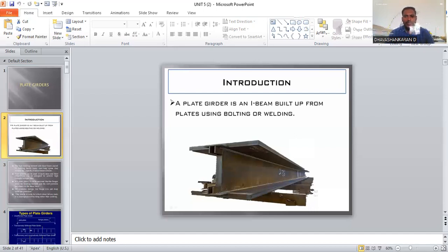These result in webs having a shear failure mode by buckling rather than yielding. It means that when we provide a good amount of steel, that is, the flange size and web that we provide, it can resist buckling and also yield at high strength, so it does not undergo failure.